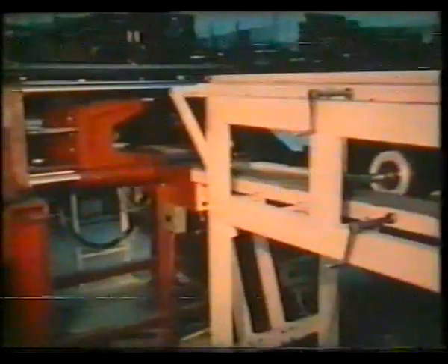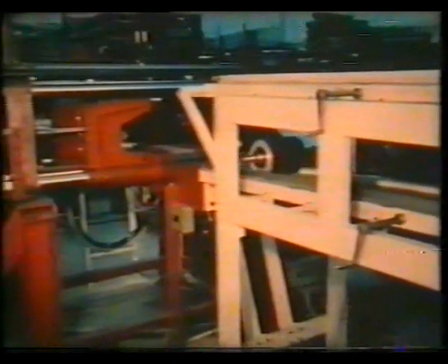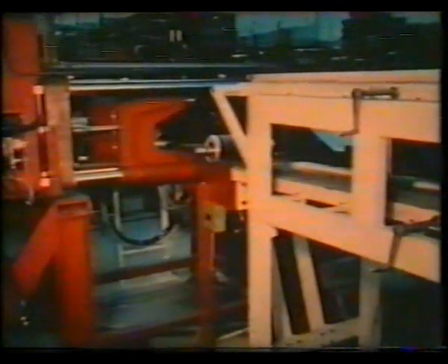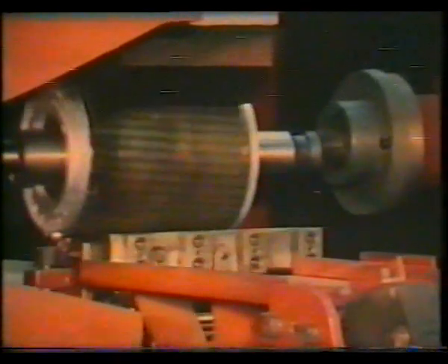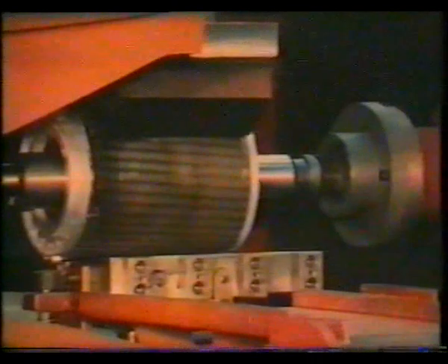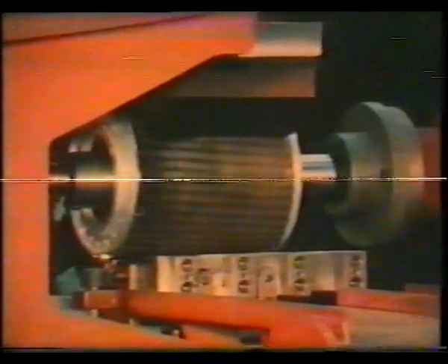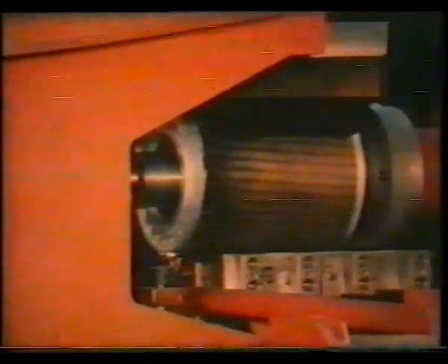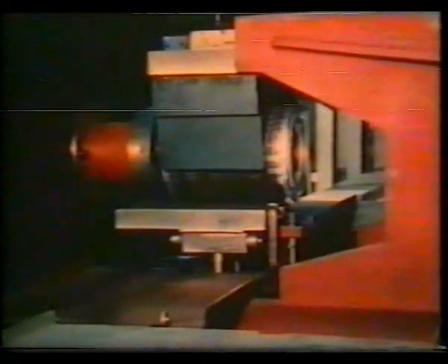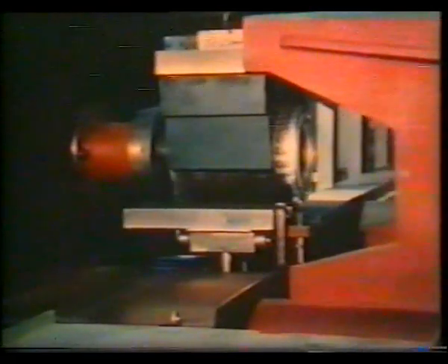This is a rotor rolling into the mandrel removal station. The individual rotors leave the buffer zone and enter the clamping device, where a horizontal ram presses out the mandrel. The mandrels pass through a cooling area and complete their cycle. The finished rotor can now be forwarded for further processing.